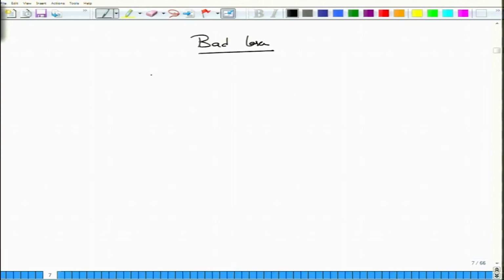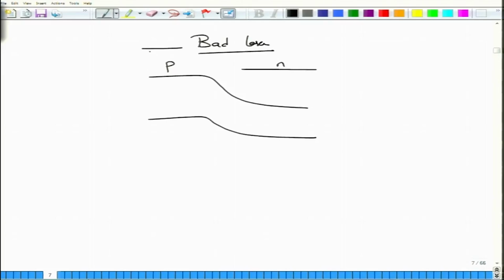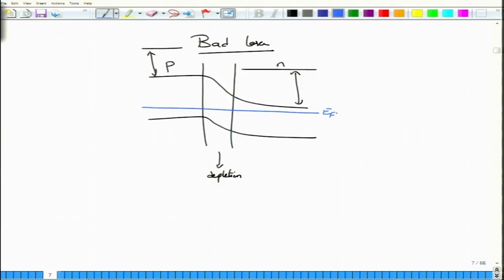You start off with a PN junction. So, you have a P region and an N region here, and this is an energy band diagram that you already know. Somewhere above will be the vacuum level. We have already talked about those vacuum levels. And this of course is the energy gap that you have. This region in between is the so-called depletion region, under the equilibrium condition. Under the equilibrium condition, you have the same Fermi level everywhere. It may not show it correctly, but this is how the Fermi levels are present.